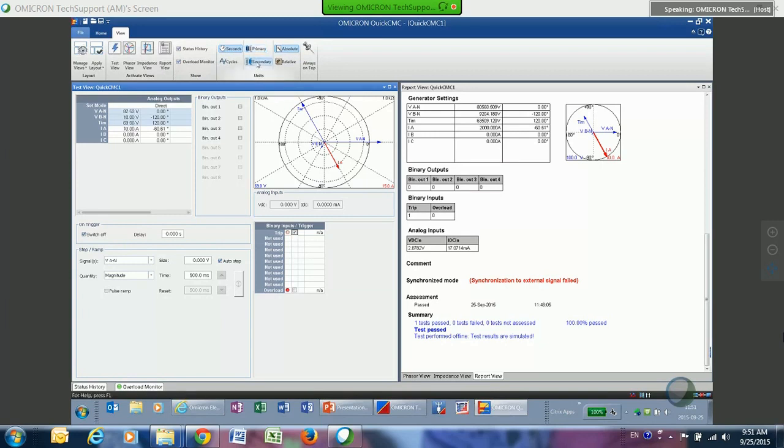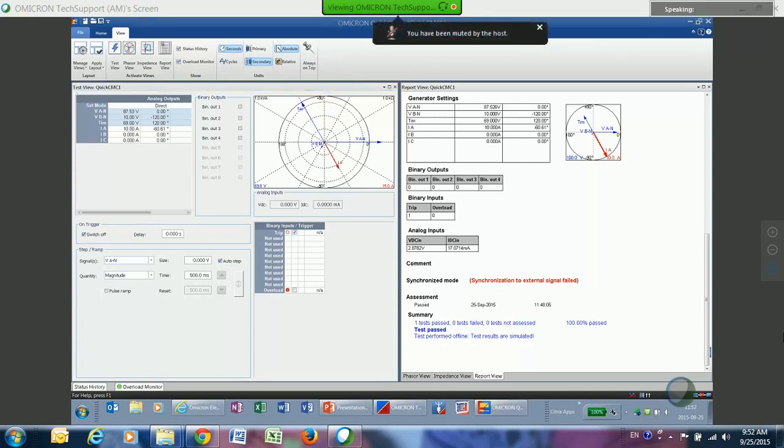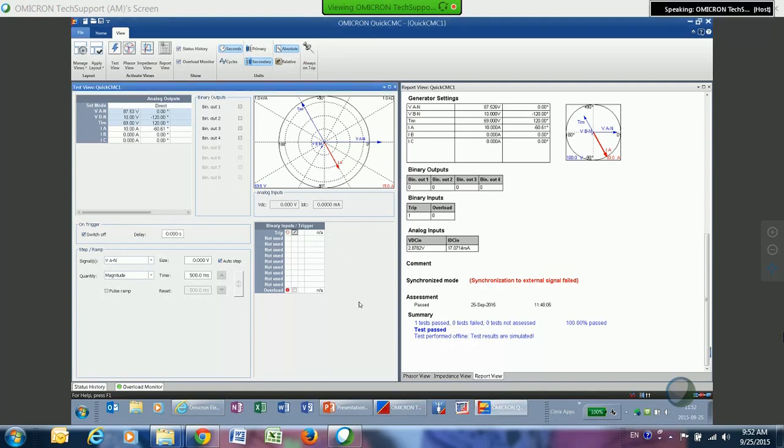A lot of times if I'm doing reclosers or even relays, maybe I want to see these values as primary values because that's what it shows on my metering. And then I could choose this window, and it's just easier for me to look at the values instead of getting a calculator out and calculating the values that I want to see. Then I can select absolute and relative out here. Usually it's just defaulted to absolute values.